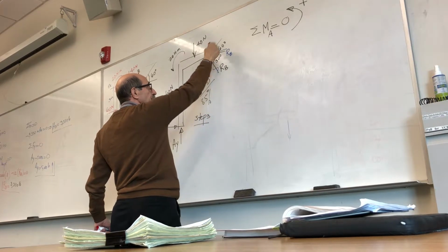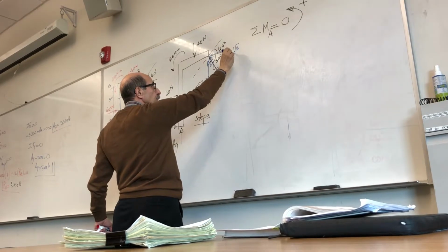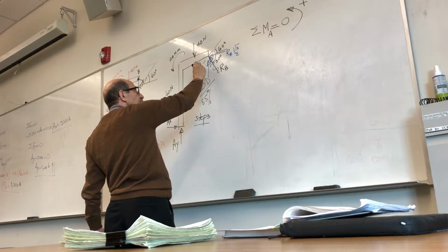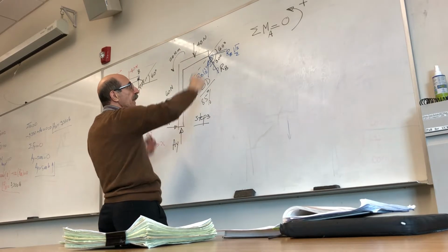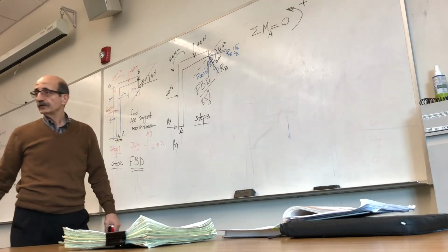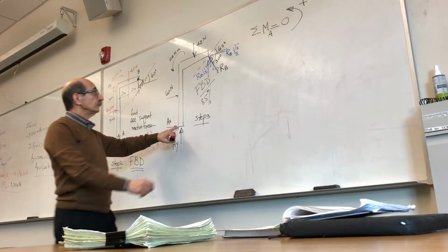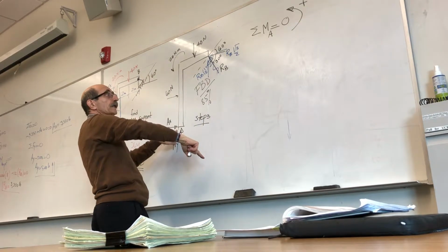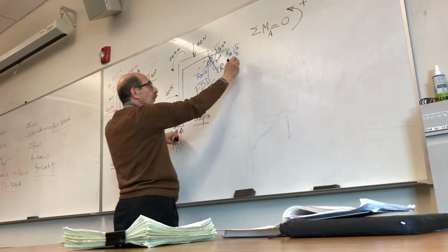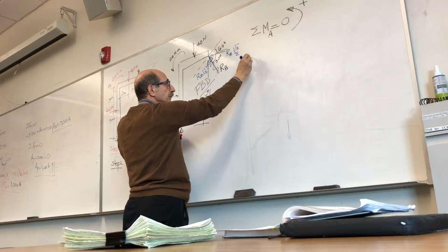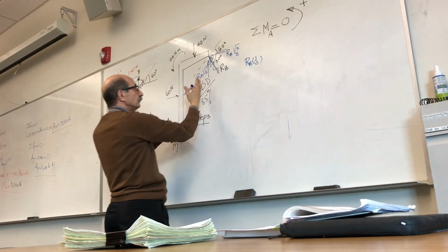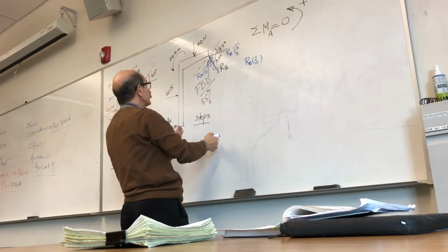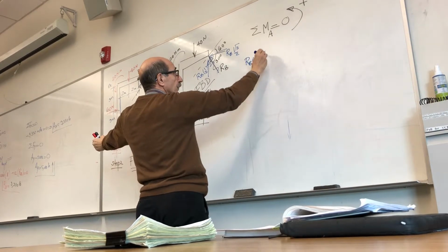So this is RB cosine of 30, which is square root 3/2. This is RB sine 30, which is 1/2. Now let's write down summation of moments about point A. This force rotates about point A counterclockwise, so you have RB half times the vertical distance from here to this line of action, which is 4 meters.